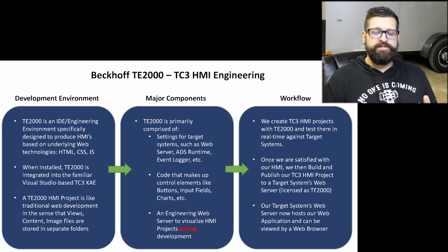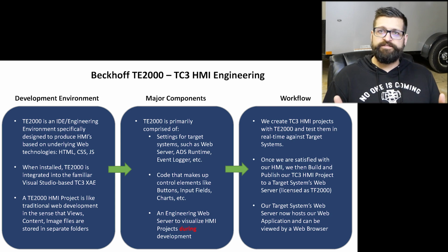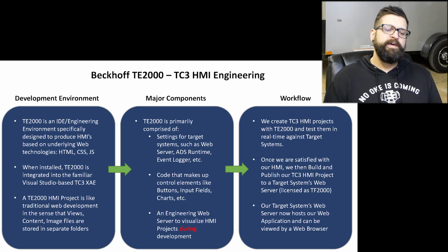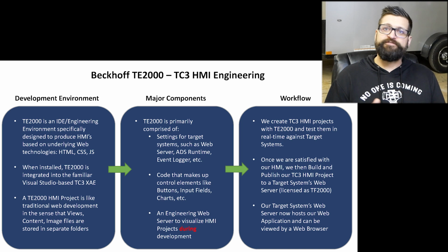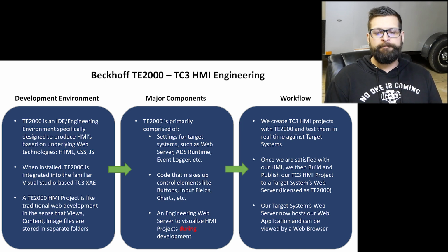Event logger information, because there's an HMI extension that will pull data from our runtimes and make that available to a control that's on the screen in an HMI. So you can see, hey, I've got these messages, I've got these alarms that I've created in my PLC, and now they're visible in a nice pre-packaged format in your HMI.